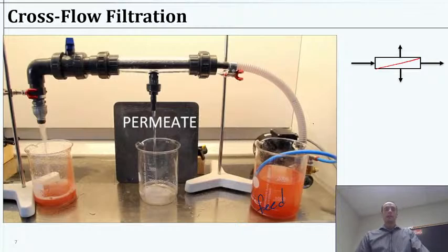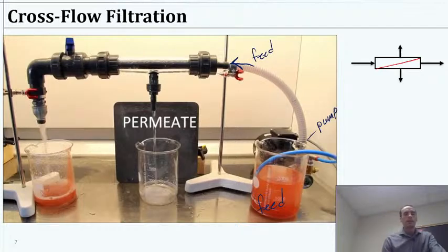And that's being taken. There's a pump, if you look back here, that's applying some pressure. So we've got our feed line coming to our membrane system in that direction. The membrane itself is housed right in here. So we've got a membrane inside there, and what it looks like to me is some tubular membrane, and we'll talk about it, but we can have membranes in a lot of different forms. So this looks to me like a tubular membrane where water's coming into the inside of the tube, and we have this system pressurized.